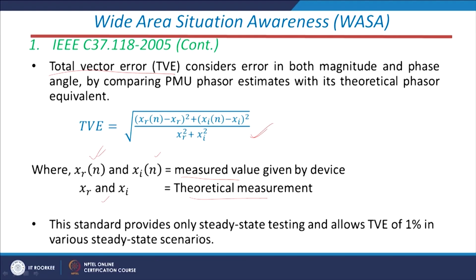Now, this standard provides steady state testing, which allows this TVE to be within 1%. Remember, this TVE is allowed up to 1%, and that is in the steady state scenario. This is not in the transient phase, it is in the steady state phase.